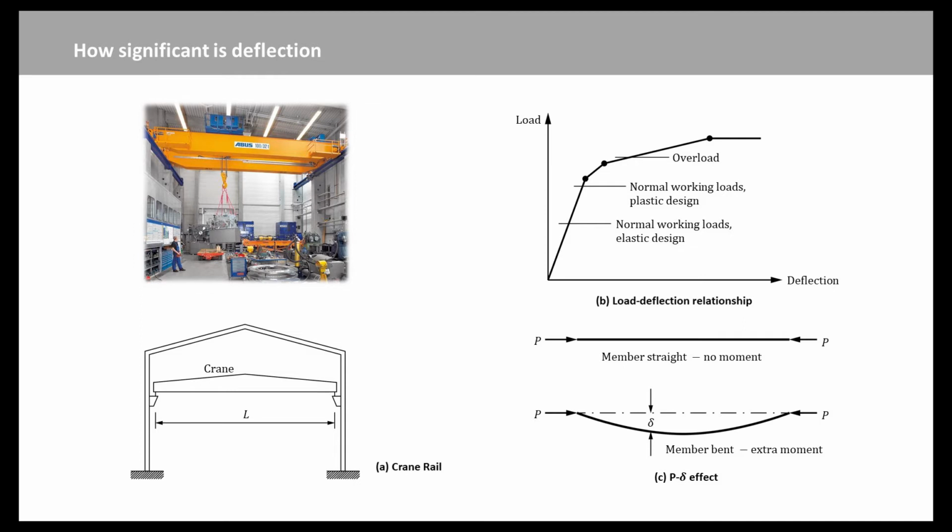There is another potentially more serious possibility. The deflections before collapse may significantly reduce the collapse load of the structure. It is well known that deflections reduce the stiffness of struts, the so-called P-delta effect, and the same thing can happen to frames. The problem is worse in more flexible structures, where the deflections can cause an unexpected collapse mechanism, owing to overall buckling instability of the frame. Imperfections in the as-built structure can amplify the deflections.